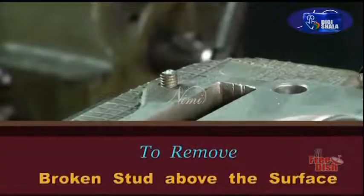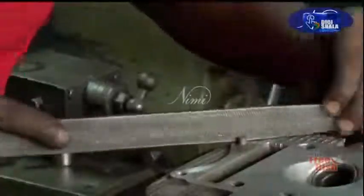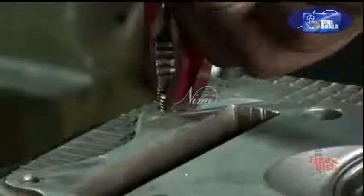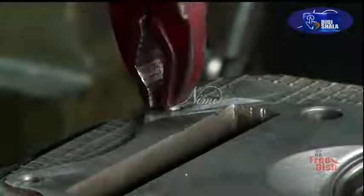Removing broken stud above the surface. File two sides of the stud flat above the surface. Use a wrench and unscrew to remove the broken stud out.